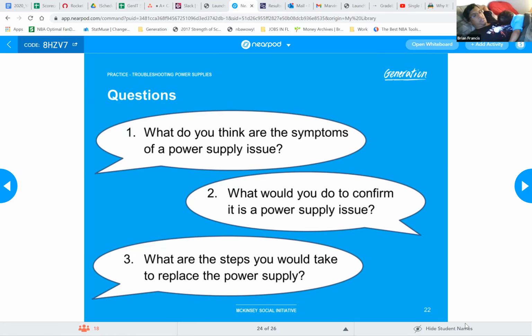I use the power supply tester, or you can take a known good power supply and put it in the computer, or vice versa, and see if you replicate the same issue in another tower. There are also simple things you can do before you yank the power supply out. Make sure it's plugged in. That's one. What's another one?